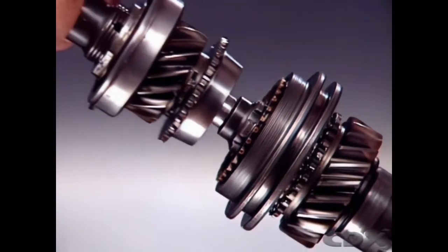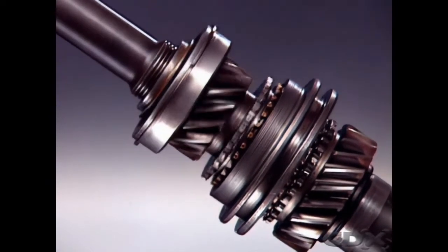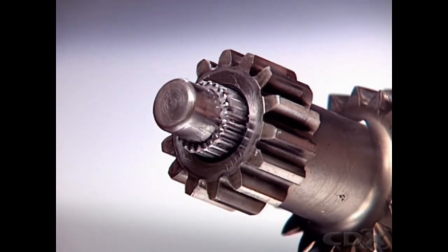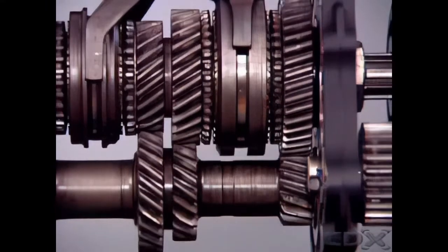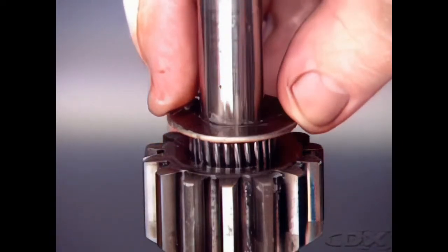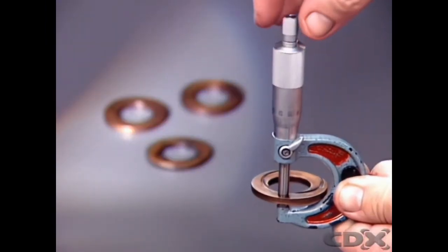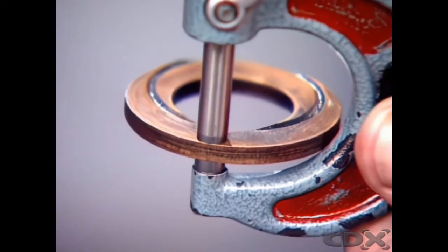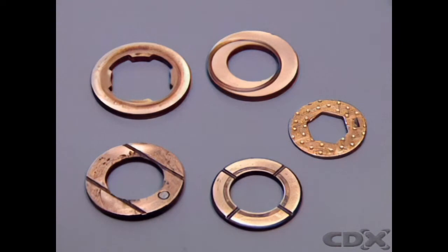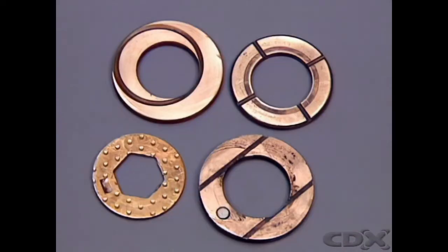Typical applications are the spigot on the front of the main shaft, supported in the rear of the input shaft, and in some cases on the counter shaft, and the freely rotating gears on the main shaft. Separate thrust washers can retain them and cater for thrust loads. They are often a selective thickness to allow for end float adjustment. Thrust washers are plain bearings. They are usually bronze, but can be steel, with the bronze facing on one side. They can be dimpled or grooved to allow for lubrication.